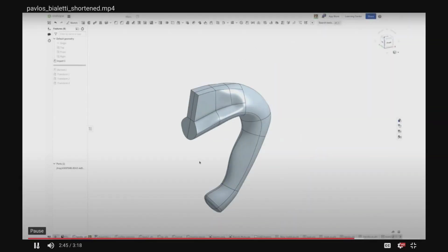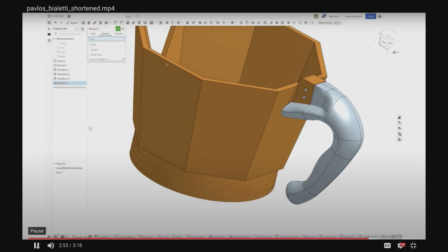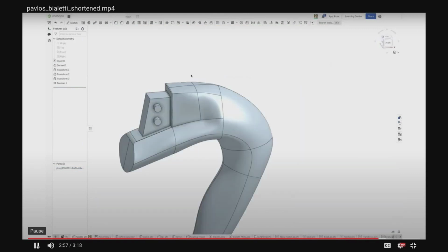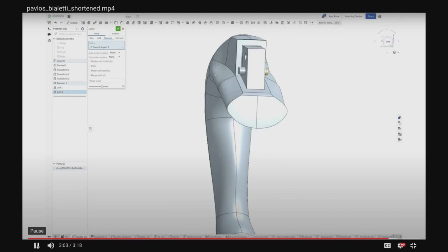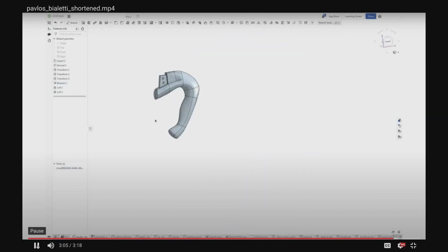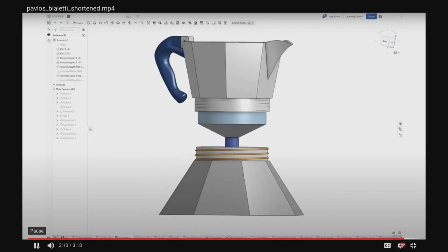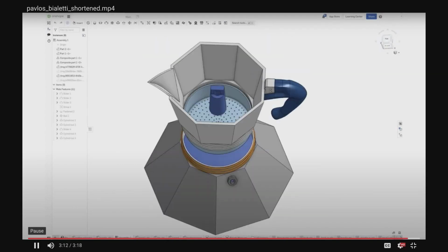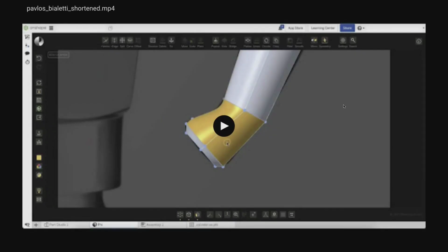And there it is in a new Onshape Part Studio. Again, he put it together with the container. As you see here, everything fits. He did some Boolean operations to remove the additional volume from the FAI part, and also he removed those cylinders to drill the holes. And the part now is perfectly ready to be assembled with the rest of the coffee maker, and this is the end product. So I think this is a good example of how you can combine working in FAI with working in Onshape and take advantage of the power of both tools.